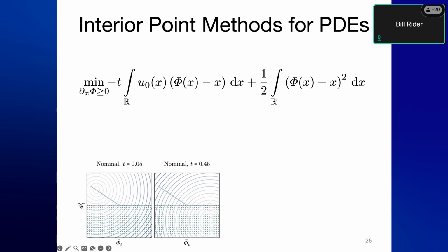I will also say that I still stand by what I said earlier: to first order, just adding the sigma to the pressure is probably a good point to start. That might give good results on a lot of problems, but at the same time we have some ongoing work that is trying to better integrate this regularization with the equation of state and the pressure. The first thing we did was just adding them up, and that gives good results in many cases, but it's not perfect yet.